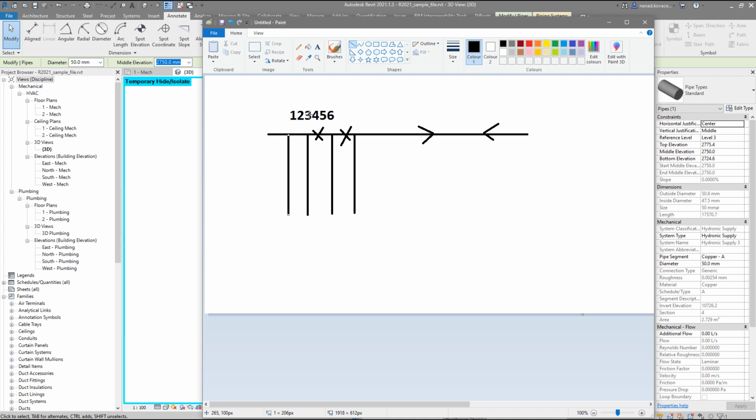So it used to be very good information if you know where your ID is. But in case you connected the pipe and you are assuming that the old ID is here, and then you sorted your new pipes to go from left to right and tell Dynamo to connect this pipe with this ID, now we don't have any relation between those pipes, and Dynamo will be unable to create those kinds of fittings over here.